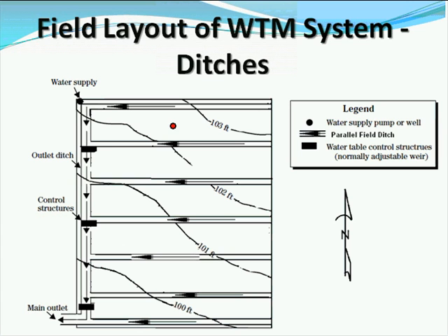And the distance up the field ditch that it would have impact would be completely dependent on the elevation set on the control structure and how far back it would go up. Also, in a surface drainage system, the impact of the water level control structure as you raise it is somewhat dependent on the volume of storage that you have in that ditch as well. So there's a little more analysis, or impacts, I guess, that need to be looked at.